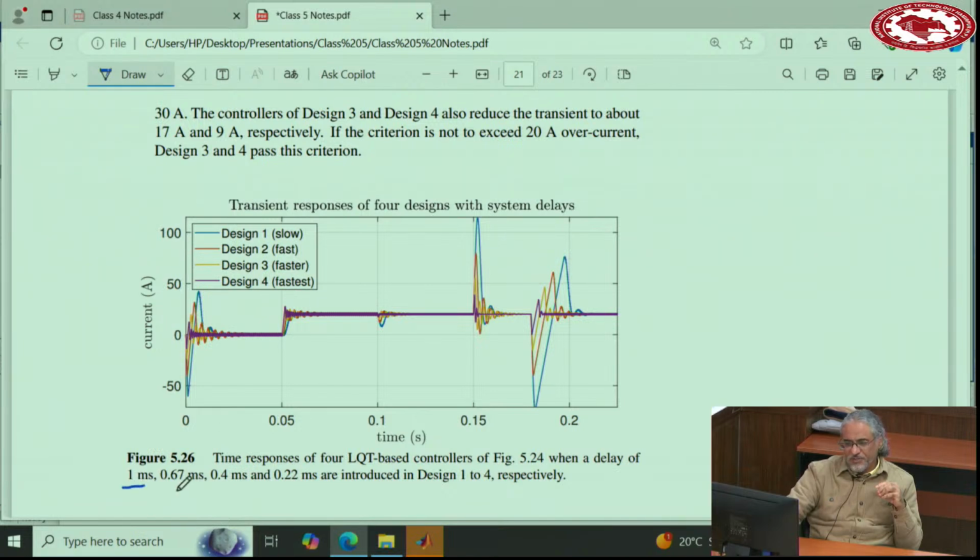Yeah, the delay margin that I said. Now, I intentionally go to the simulation and insert a delay into the control loop, and that delay models the delays of the digital control, because the controllers and simulations you see here are in continuous time, since these are easier to design and simulate. I did not use digital control. So whenever you want to include the delay of digital control, you need to go and insert a delay yourself.